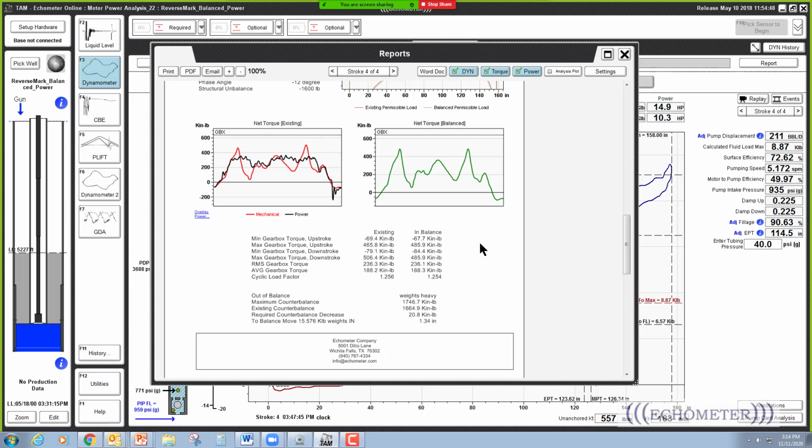I should have just answered your question and said it's important that you put the power probes on the outside of the VFD if you're going to try to study the power use. Okay. On slide 26.